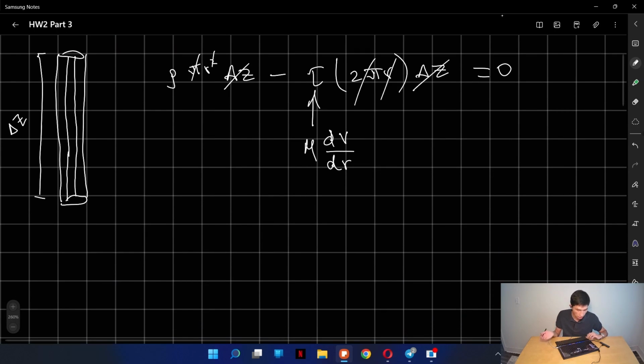So if I want to write that equation, I have viscosity times dv/dr equal to negative rho r, divided by 2, and we can also divide that by viscosity here.